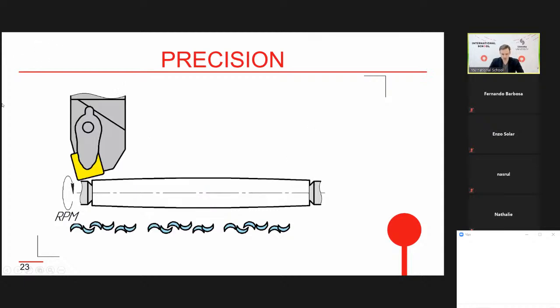Okay, so after the machining process is done and there is no acting force, the shape will be like this. In Russian, we call it a barrel type error. So the real shape is not a cylinder, it's a barrel type shape, or a shape with different diameters. Here we have one diameter, here we have the maximum diameter, and so on.